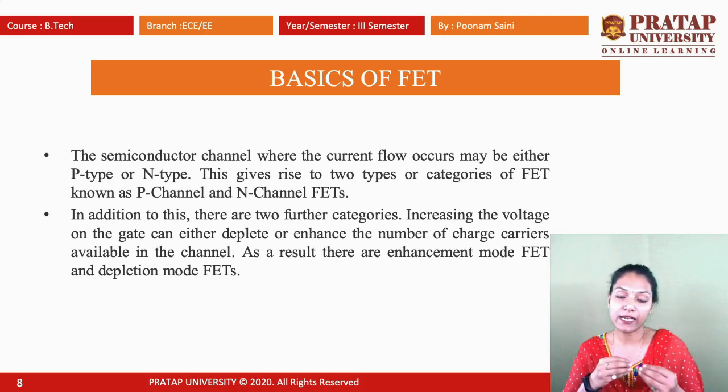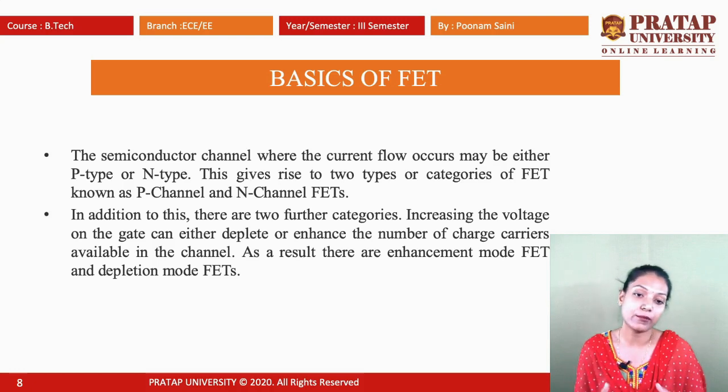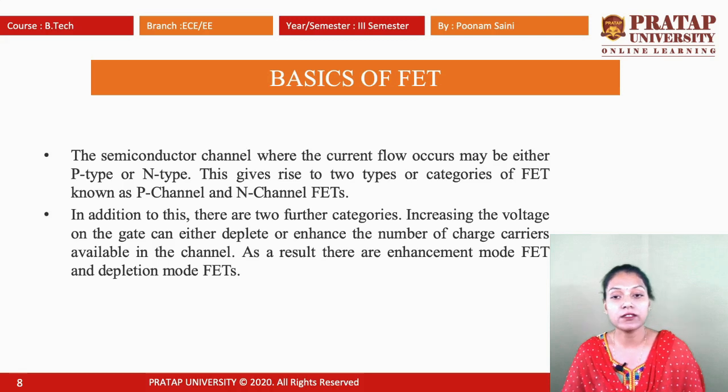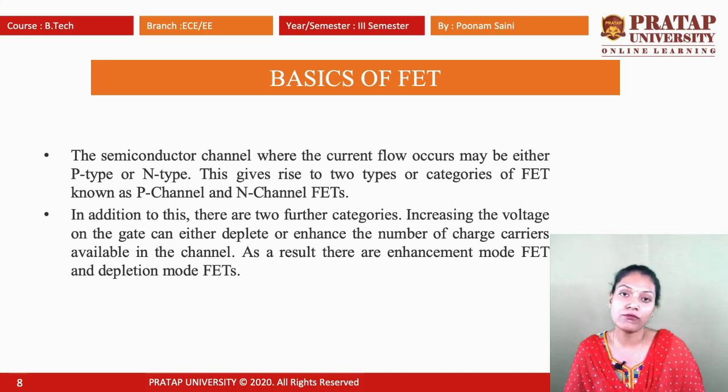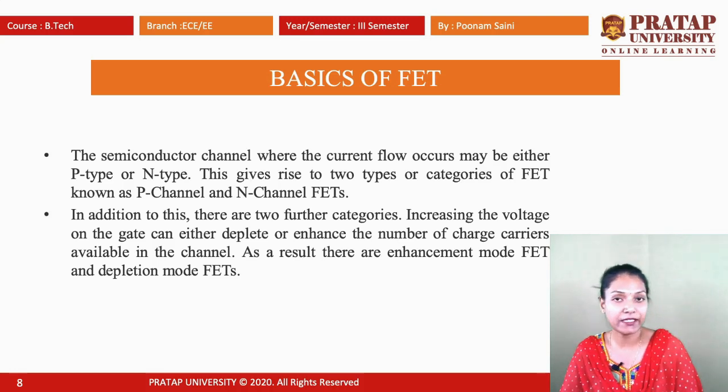There are further categories. Increasing the voltage on the gate can either deplete or enhance the number of charge carriers available in the channel. As a result, there are two types: enhancement mode and depletion mode. As the number of carriers increases or decreases, the operation of the FET changes, either in the form of enhancement or in the form of depletion. So we discuss two forms: enhancement FET and depletion FET.